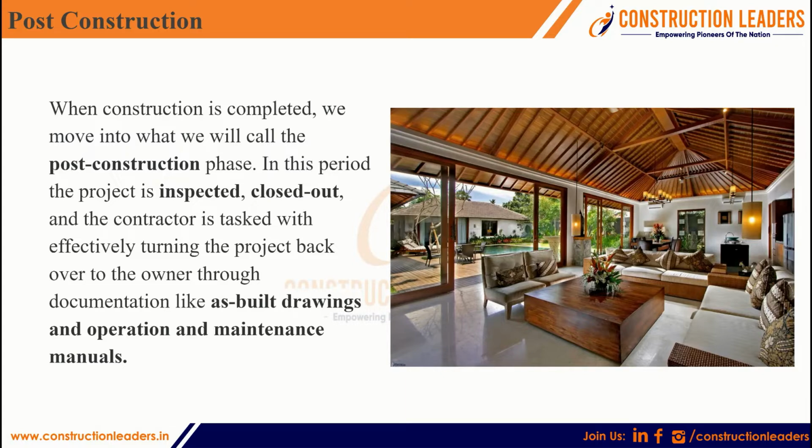The first design intent drawings are different, design development drawings are different, good for construction drawings are different, the fabrication drawings are different. Changes will be happening all over the construction phase. Everything needs to be recorded, and after the construction of the facility, we should work on the drawings again. We should update all the drawings and submit the operations and maintenance manuals along with the drawings to the owners.